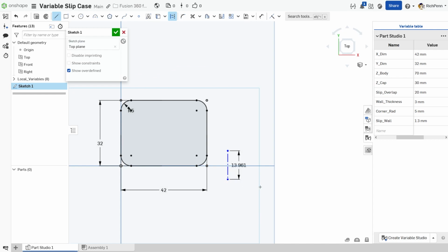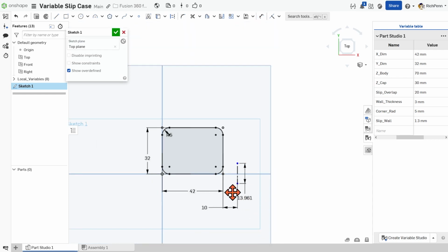and hit the enter key, and then do a dimension and dimension it at some distance. It doesn't matter. I'm going to put 10 in because 10's a real good number. And we're ready to go. Now we can mirror this part across this line over to here. And I will show you why that's important.